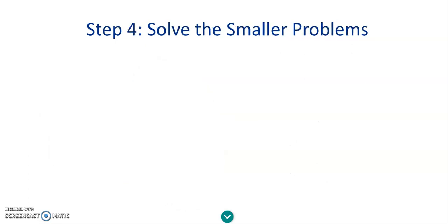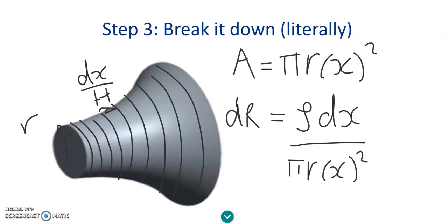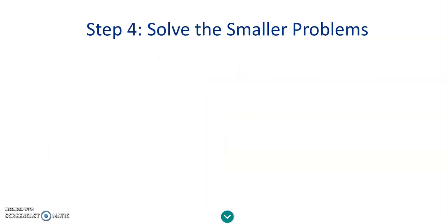How do we then use this to find the total resistance? Well, what we do is we sum these up across the whole length of the shape, and when we sum up very small elements, that's actually called an integral. That's what integration is. It's not very well taught at school in my experience, but we'll find that we can get the total resistance by actually integrating dR, or summing up all these small resistances.